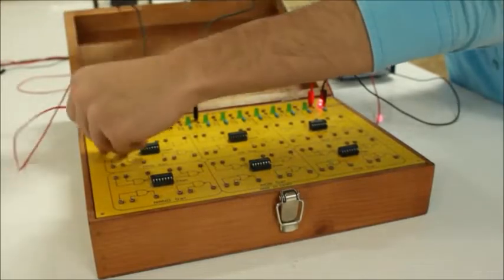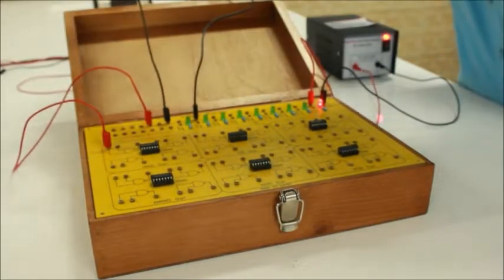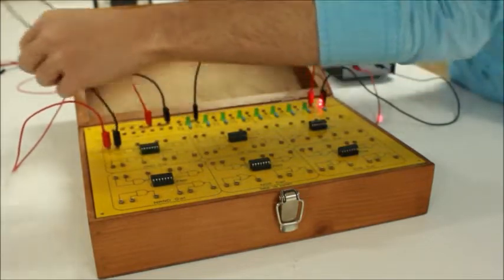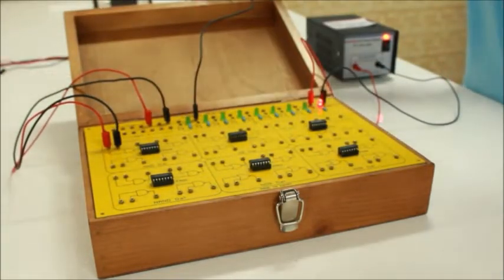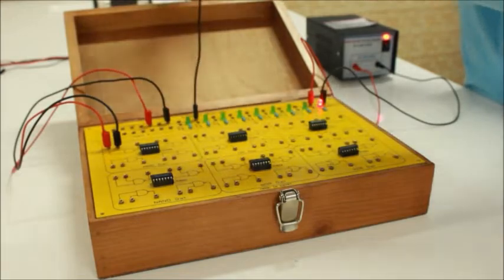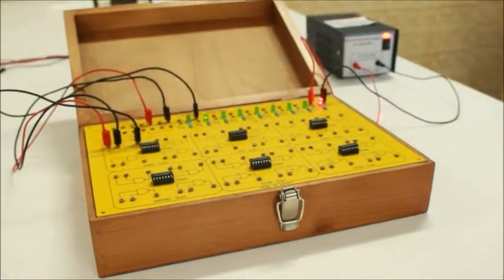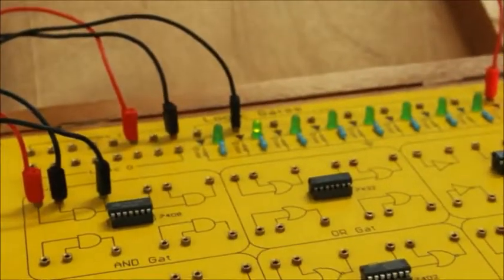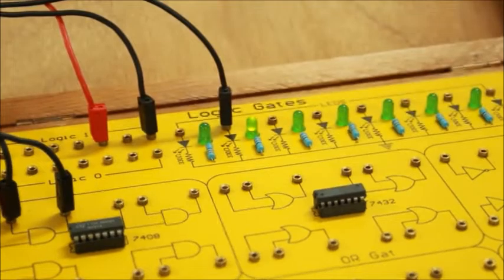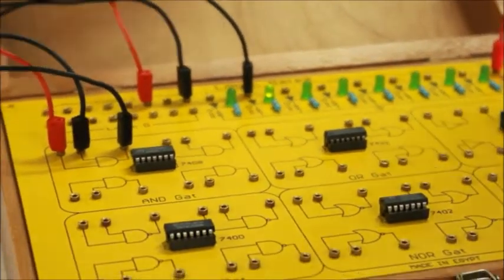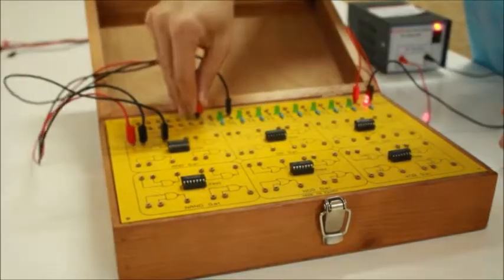The logic gate is an elementary building block of a digital circuit. Most logic gates have two inputs and one output. At any given moment, every terminal is in one of two binary conditions, low or high, represented by different voltage levels. The state of a terminal generally changes as the circuit processes data. In most logic gates, the low state is approximately 0 volts, while the high state is approximately positive 5 volts.